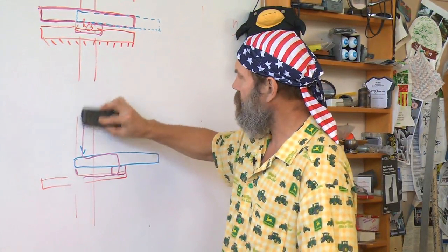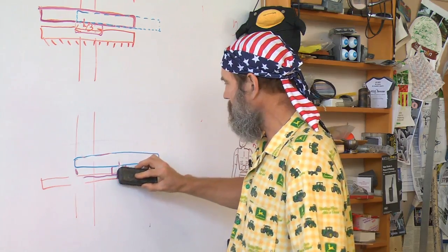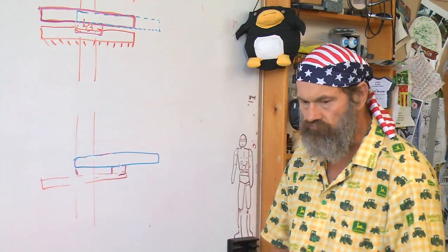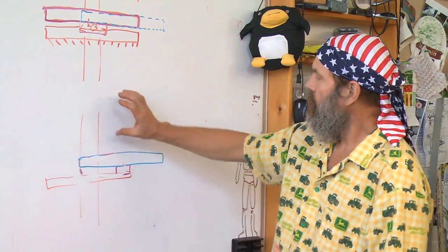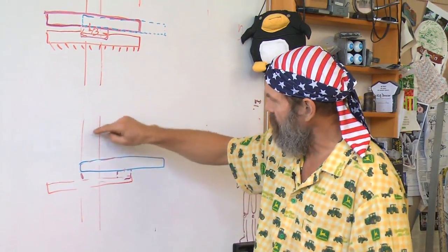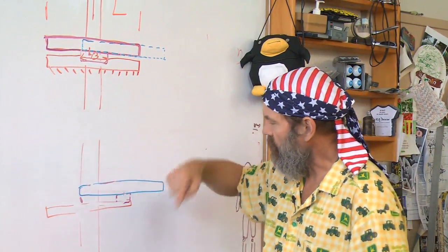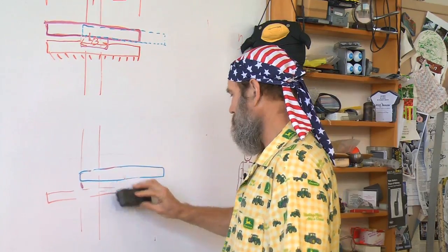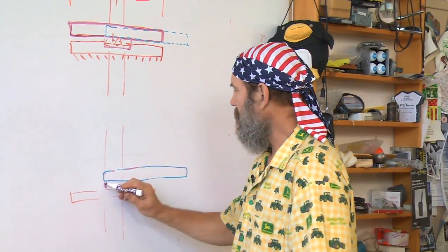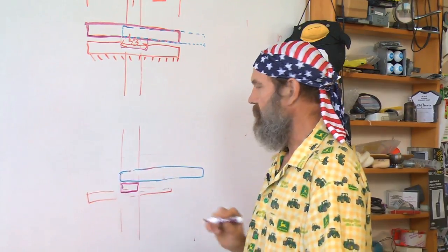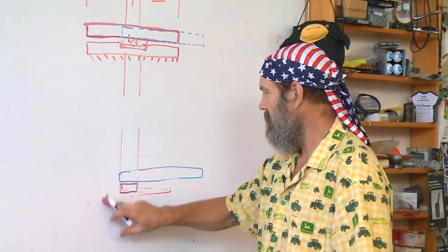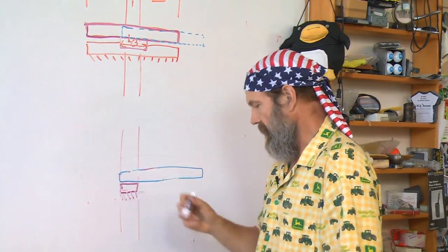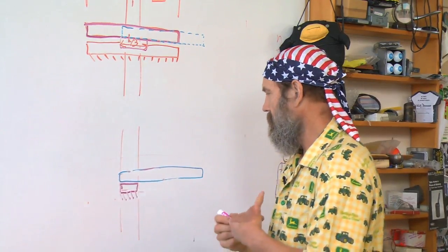How do we keep a tighter structural loop as we're sketching out a design? The bearing block, the flow of forces, we want to always go from the tool into the part right back into the structure. Tight structural loop as opposed to this. So that tells me topologically in my brain, because I'm feeling the forces, that I'm going to keep the bearing block here, which means that a better design is to fix my bearing block and then have the rail for the bearing block on the table.